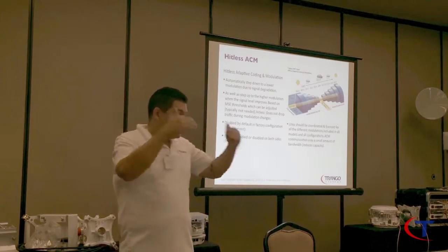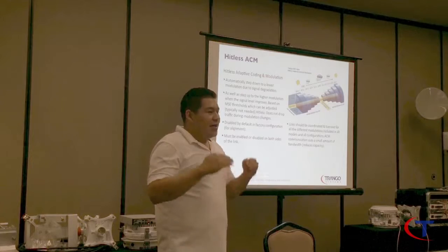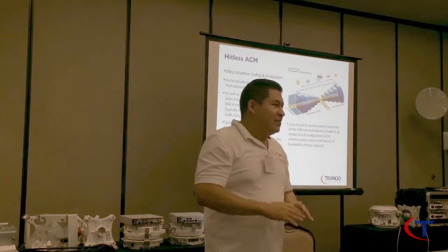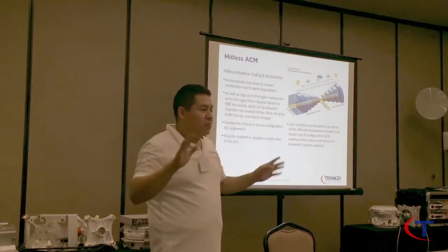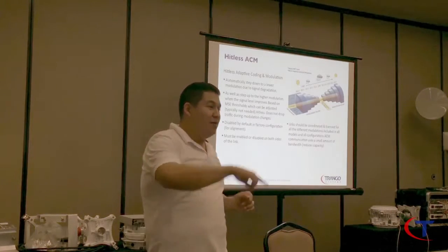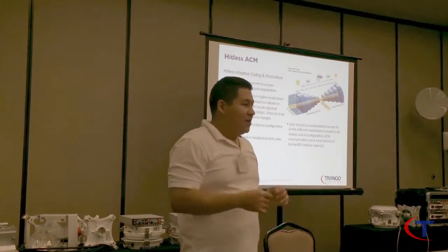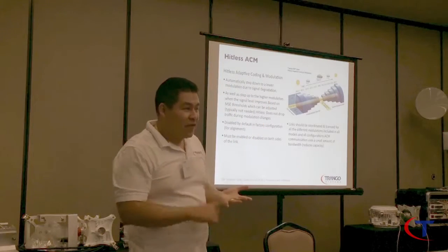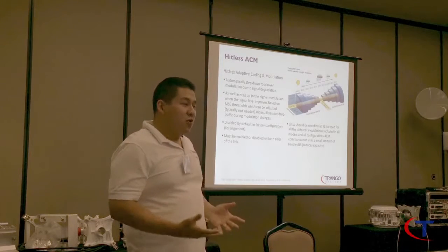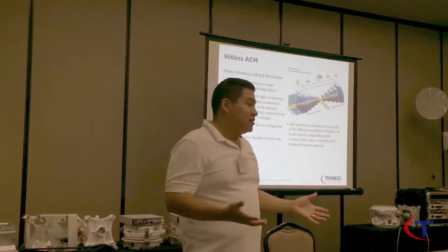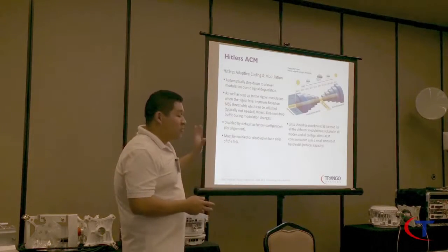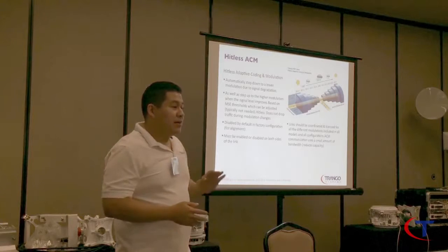When it starts getting dark, it gets cooler. In that middle point transition with the hot and the cold, the RF just goes up and down, and you will see it. If you monitor the link, you will see the RSSI go up and down, up and down. You're like, what's going on? Is something failing? My power supply is gone, my ODU is going bad, what is it? No, it's actually ducting because of reflection from thermal inversion. Now, the radio ACM goes up and down by itself.